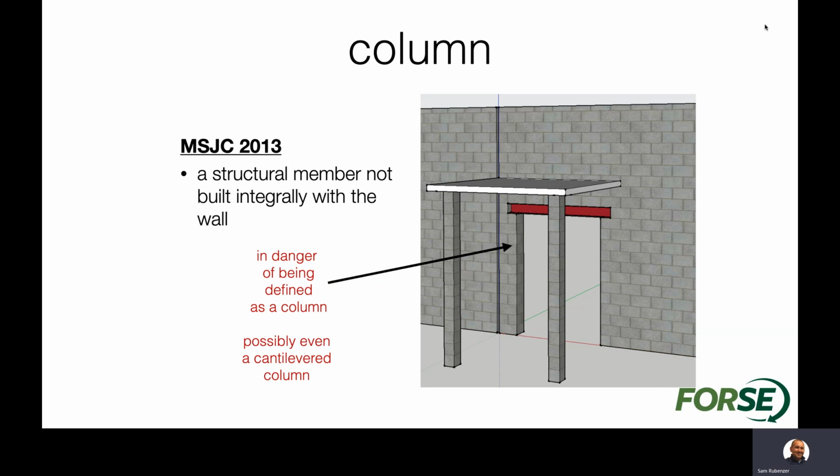I think there can be a time, though, if we use some other material for the lintel, a precast or steel element, then you possibly could get into a situation where that part of the wall that used to be connected to the lintel and connected to the wall above might start to be more and more isolated and maybe need to consider that as a column. So the different types of lintel choices that you make can have some bearing on how you design that element.